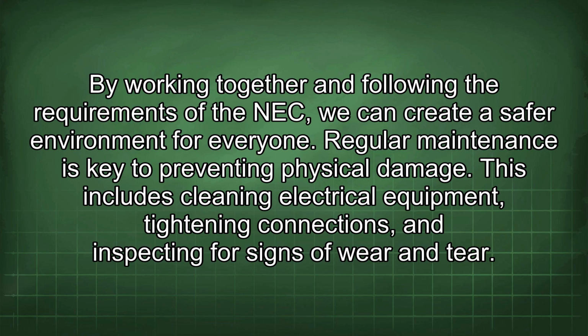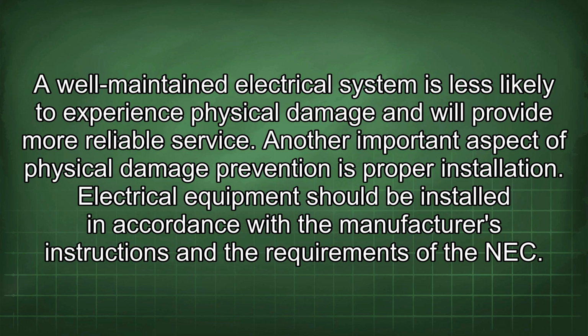Regular maintenance is key to preventing physical damage. This includes cleaning electrical equipment, tightening connections, and inspecting for signs of wear and tear. A well-maintained electrical system is less likely to experience physical damage and will provide more reliable service.